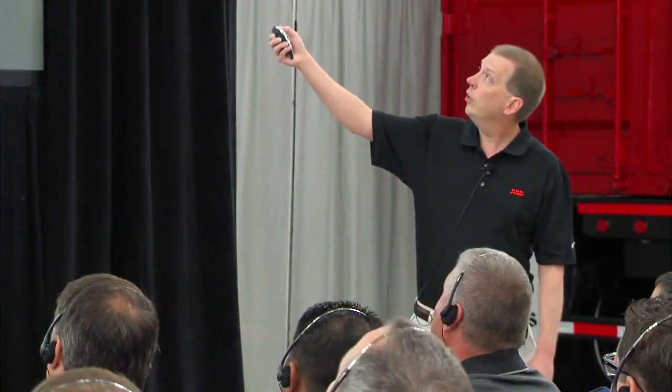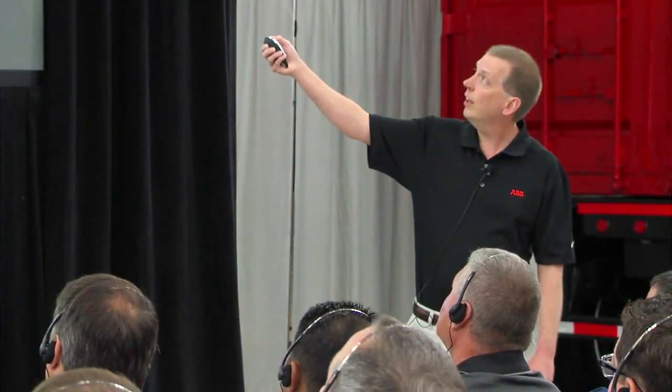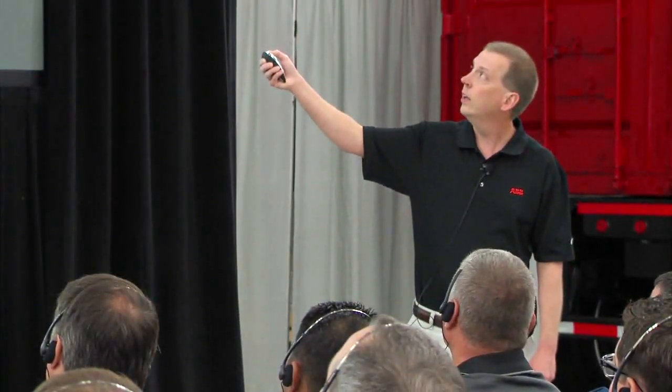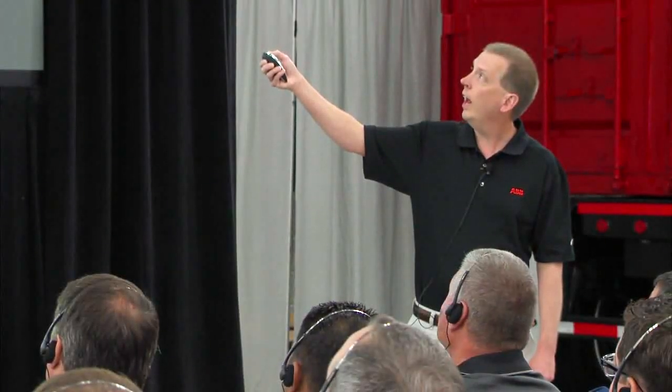For example, if you can run even 20% less speed than full speed, you're going to consume about half the energy. The reason that works is you take the speed fraction and you cube it. Excuse me, say that again. You take 0.8, about 81% speed, and cube it, and it's going to be about half energy.